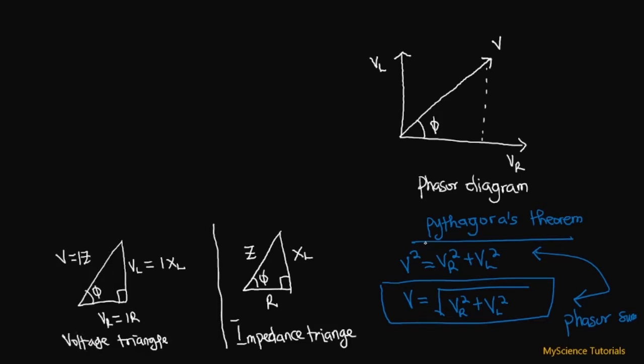All right, so now that we have this space, let's look at how we find the phasor angle over here. Now we can see that in this type of circuit, we only have our inductive voltage and then the resistive voltage. So this is the opposite side of the triangle. This is the adjacent side of the triangle. So the trigonometric ratio that will give us opposite and adjacent is what we call tan.